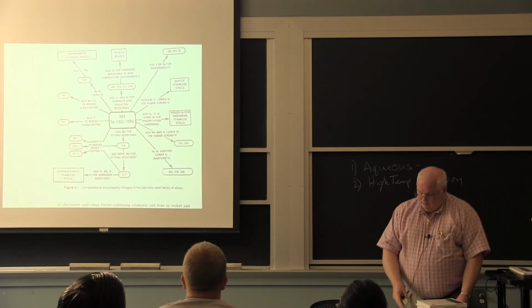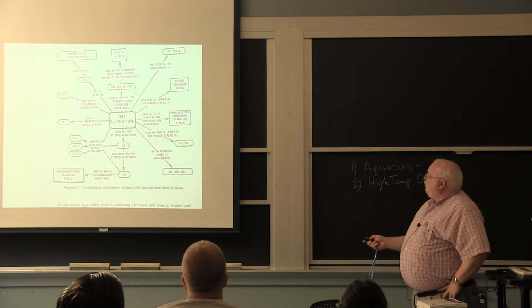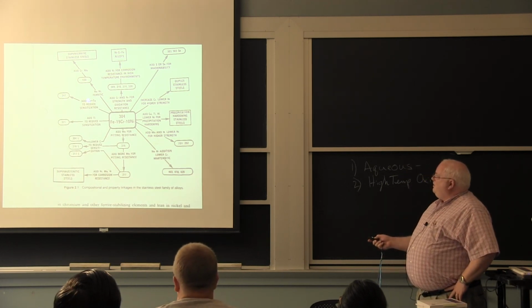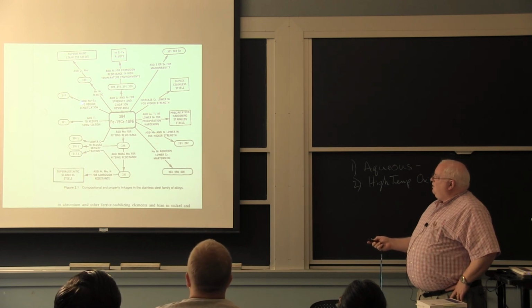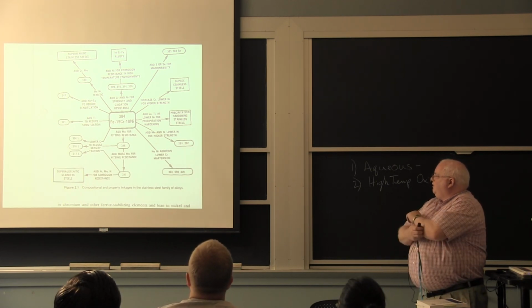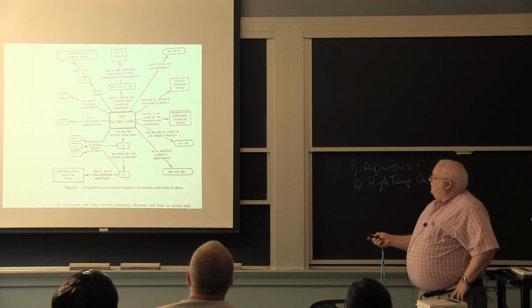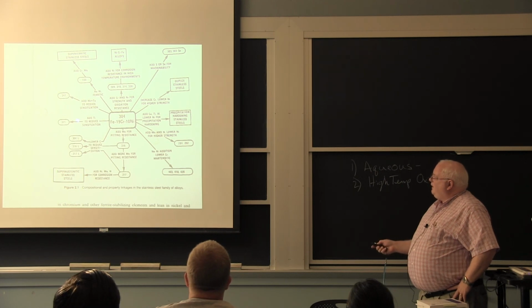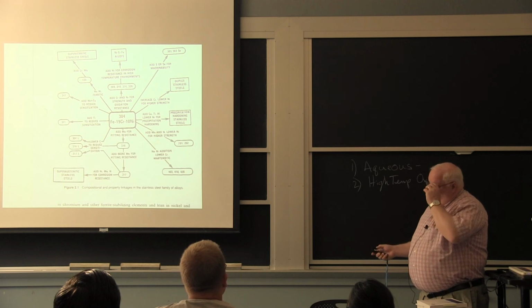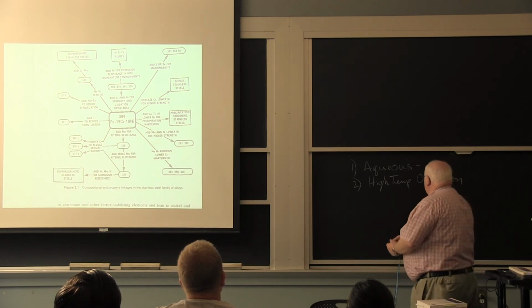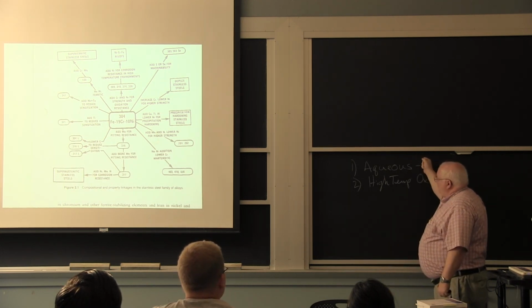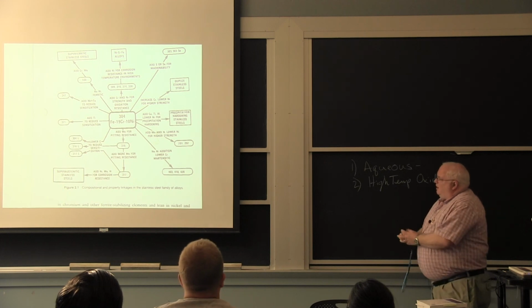And then they also came up with 347. They added niobium and tantalum, which are strong carbide formers, which does the same thing as titanium. So all of this down here is basically ways to get around the welding problems of chrome carbide precipitation. We call it sensitization. And it's a problem for aqueous corrosion resistance of stainless steel.